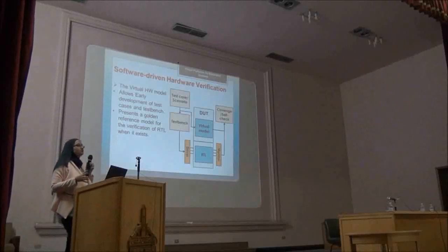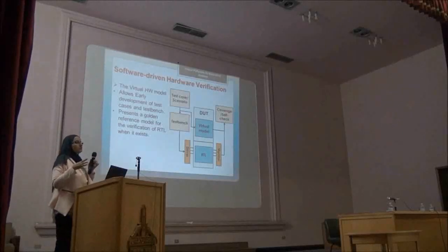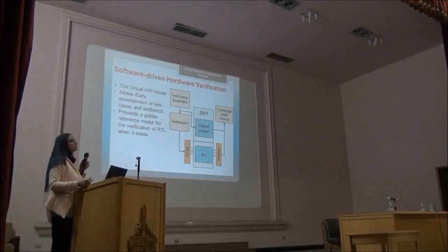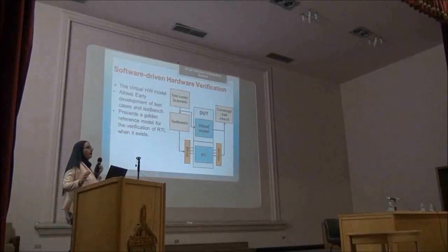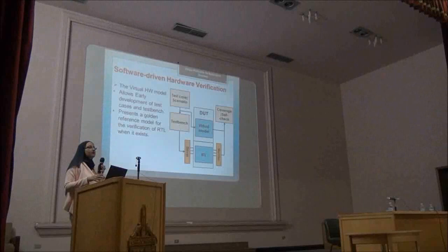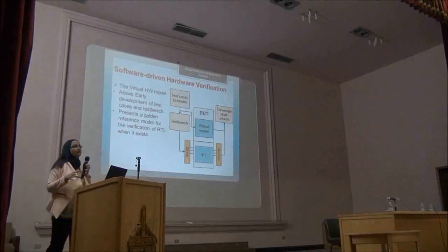Then I drive both models with the test cases, scenarios, and test bench I want, and compare the results between the virtual model and the RTL model to verify that the RTL model is working correctly.